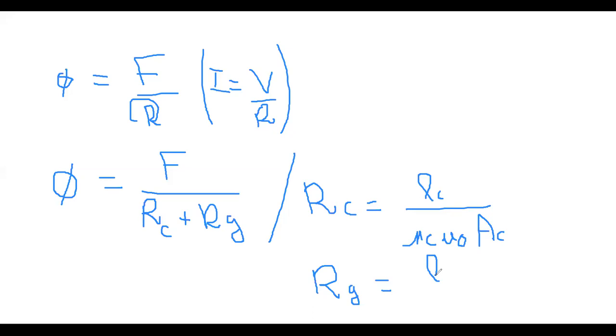But how long does the air gap need to be for each area? I didn't get the question. Can you ask in a different way? Sir, she is asking about the air gap, how big does it need to be to consider it. Like when we put AC equal to AG, we know it is for a small gap, but how big does it need to be to not consider AC equal to AG?